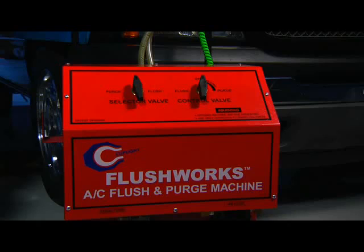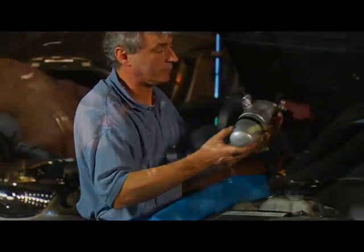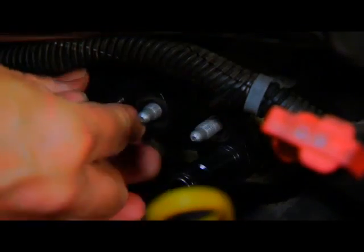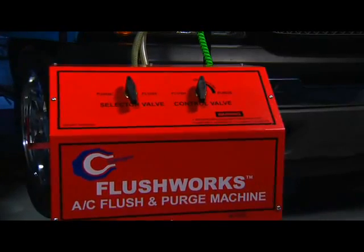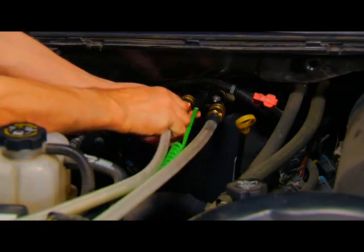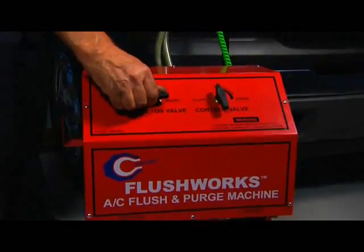In this scene, a clip-light power flush machine is used to clean this evaporator. With the accumulator and orifice tube removed, install the adapters to the inlet and outlet of the evaporator. The shop air supply is then attached to the power flush tool. Next, connect the inlet and outlet solvent lines to the fitting at the evaporator. Set the machine control valve to flush and open the flow valve slowly.